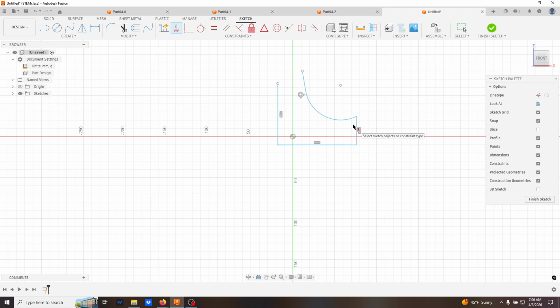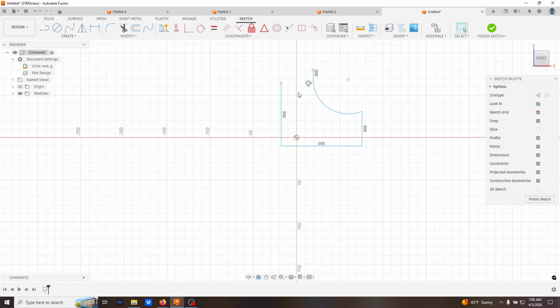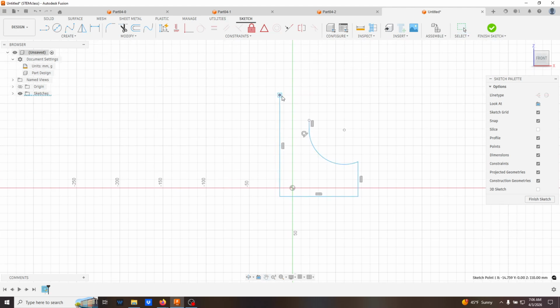It's interesting when you're doing the drawings and it throws in the auto perpendicular and parallel constraints. Those things really bug me because it'll create relations sometimes. You'll just be drawing stuff and then your drawing will be over constrained, and the reason is that it put in a perpendicular or parallel constraint that you weren't particularly noticing.